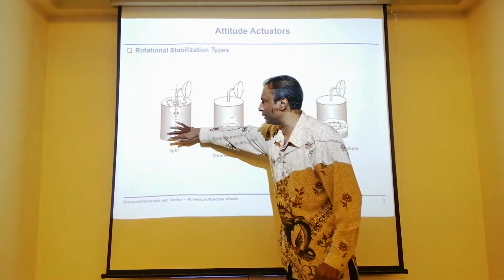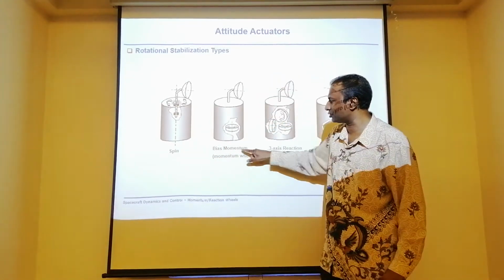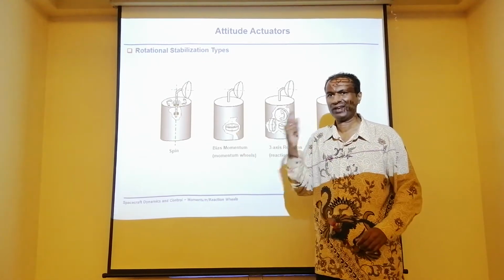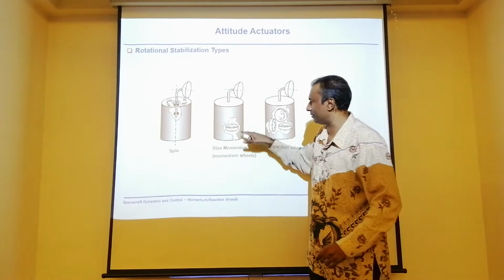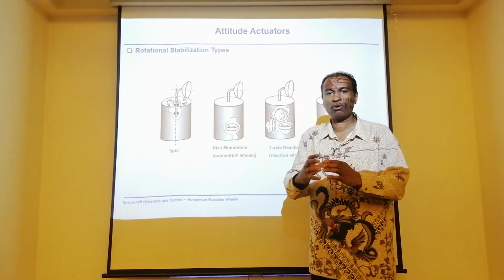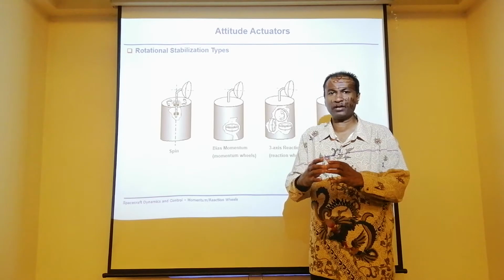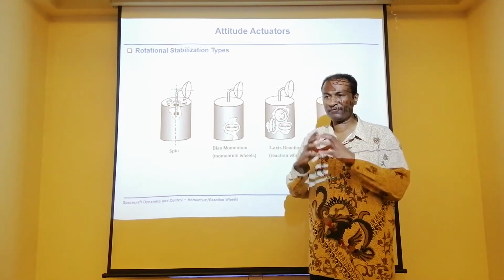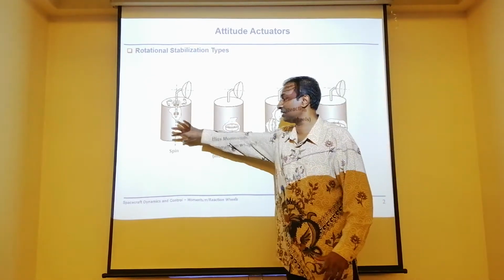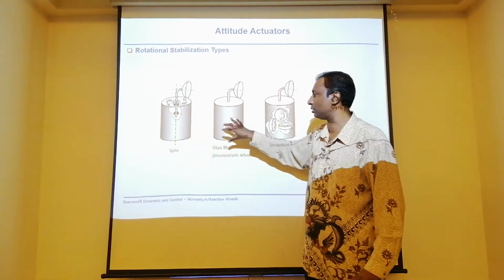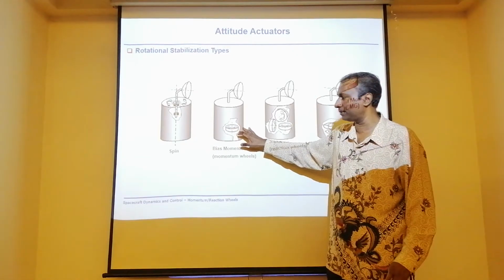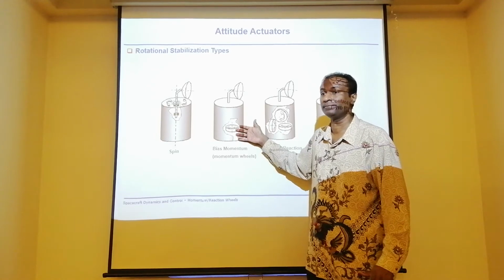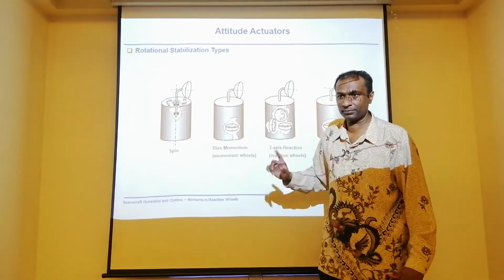Another way we do it, we stop spinning the body, install something called a wheel inside here, and command the wheel to spin very fast, to compensate for the small inertia that the wheel has. So it has to actually spin faster. When it spins faster, it can produce a similar or even more amount of angular momentum that you need. So the passive stabilization can work. It can also produce the gyroscopic stiffness here. So this is the bias momentum type 2.